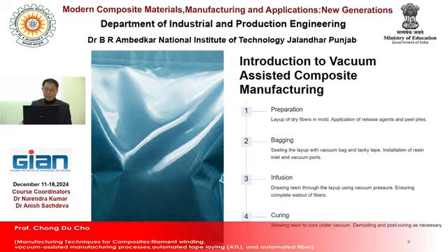And the advantage of this kind of technique is that it can provide higher quality as a result: reduced voids and air traps, improved fiber-to-resin ratio, enhanced mechanical properties and surface finish. And cost effectiveness, because it has no upper mold and the pump is not needed, differently from RTM. So lower material waste and labor cost.